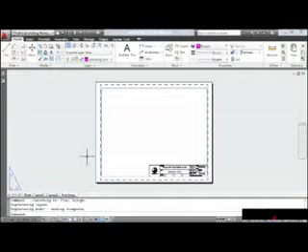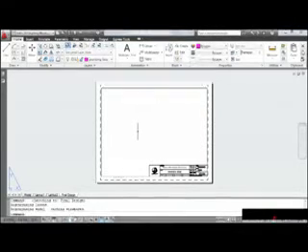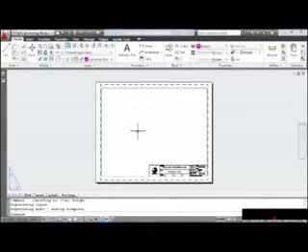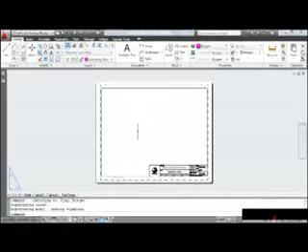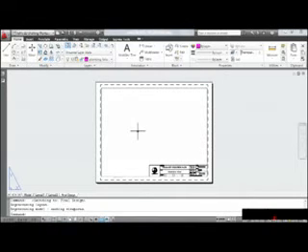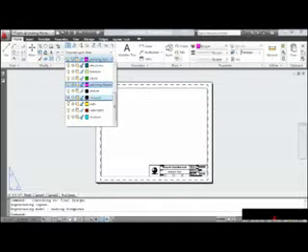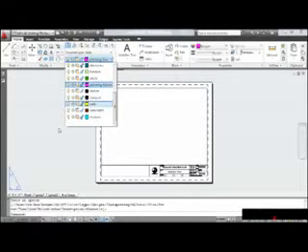It's important to note that if you copy a layout from one drawing to another, the only geometry that comes along is the geometry that exists on the layout. All of the model space geometry is left behind. You know, I seem to recall that this layout also contained a viewport, and I remember turning that layer off. So I'm going to open up the layer control, and I'll turn layer viewport back on.